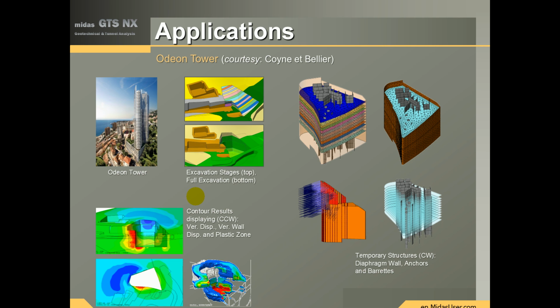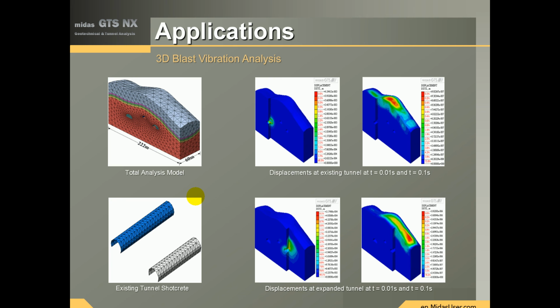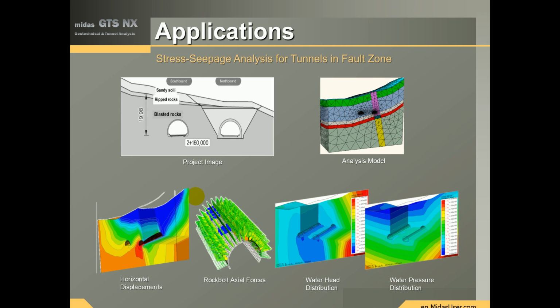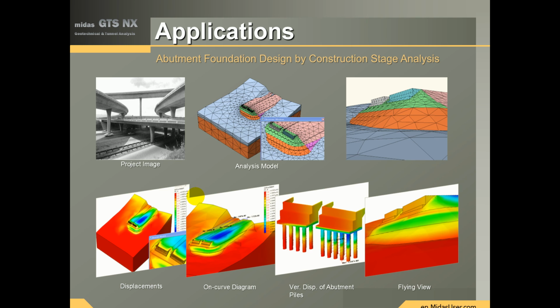The Odeon Tower, where you can see the construction stage analysis being carried out with temporary supports to the structure. 3D blasting and vibration analysis being carried out in tunnels for the excavation, stress-seepage analysis for tunnels in fault zones, and with the rock bolts and everything, you can see at the bottom images there, and the pore water pressures, abutment foundation design by construction stage analysis,